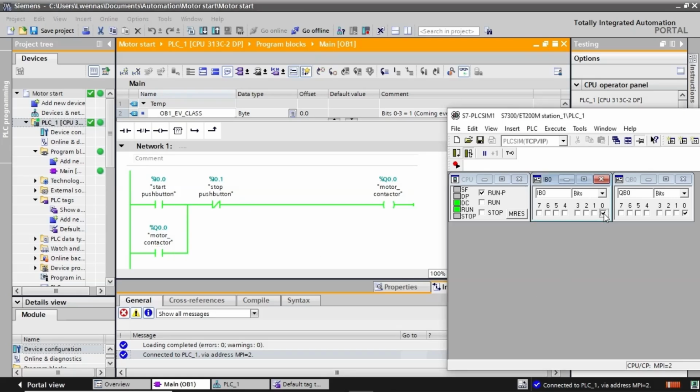Now you can see that even if we release the push button, the motor is still active. Now if we want to turn the motor off, we need to press the stop push button to cut off the power to the outputs. A critical point to add is that if we need to energize the output again, we need another press on the push button. The program as it looks ran well, however, there is something missing.